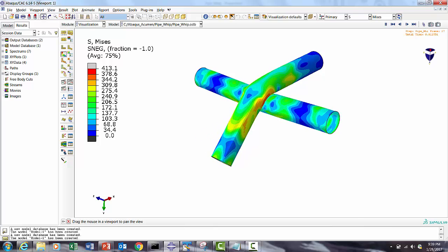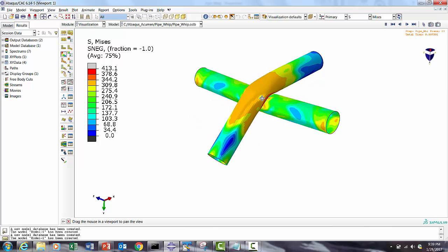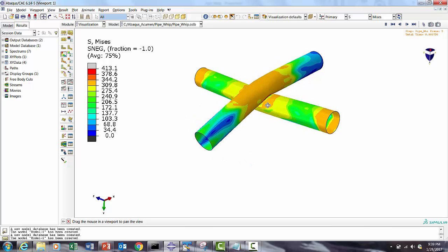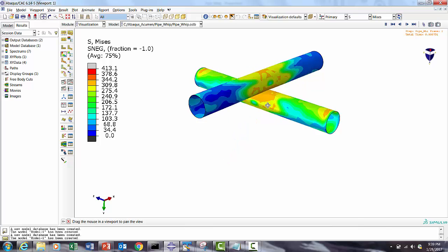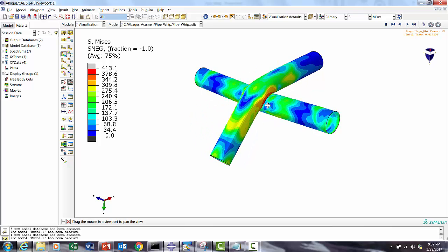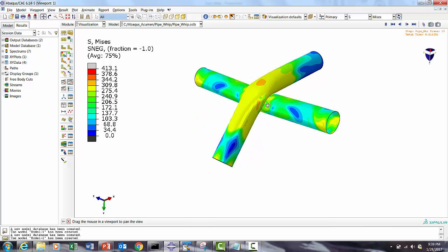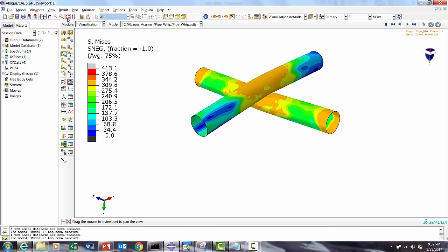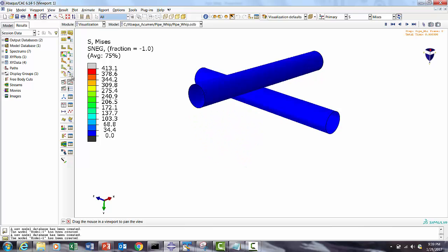The other thing we are going to do is look into the energy balance, because in this high deformation impact problem there are chances you may get a lot of hourglass. So how to control the hourglass, looking into how the overall simulation looks, whether the results are accepted or not, how much hourglass energy is generated. All those things we will look at. So this problem we are going to do in today's session.